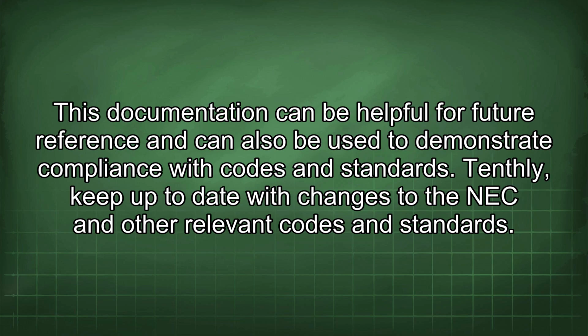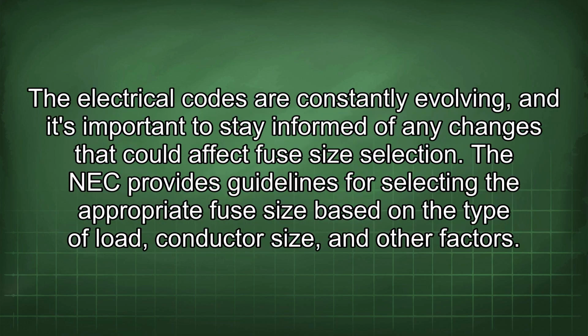Tenthly, keep up to date with changes to the NEC and other relevant codes and standards. The electrical codes are constantly evolving, and it's important to stay informed of any changes that could affect fuse size selection. The NEC provides guidelines for selecting the appropriate fuse size based on the type of load, conductor size, and other factors.